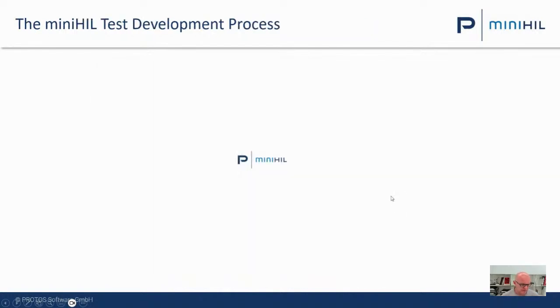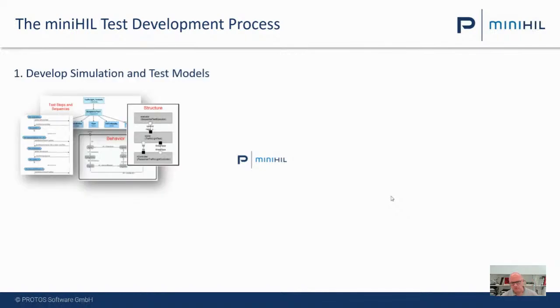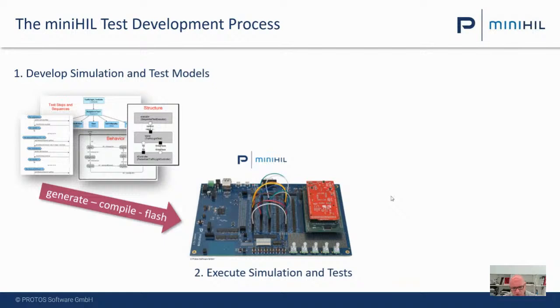So how do we do this? We have a completely model-based approach for the I/O access, for the environment simulation, and for the test cases. So we develop structure and behavior for the simulation and for the tests as models. From those models, we generate C code, compile it, flash it, and we run it here on this microcontroller.